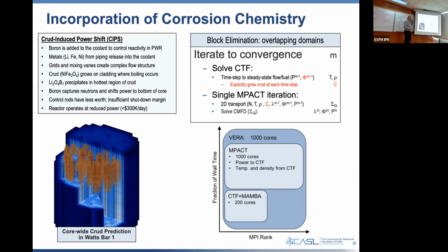There's lots of physics that went into it, and a lot of physics feeding in, this is the data you use for it. But effectively, you had this one-dimensional code, but there were millions of those calculations happening all the time because you had lots and lots of faces on these fuel rods. But because it was Fortran and because Cobra was already doing time step to steady state, it wasn't solve for me the steady state temperatures and flow conditions. It was doing let me march in time to steady state.